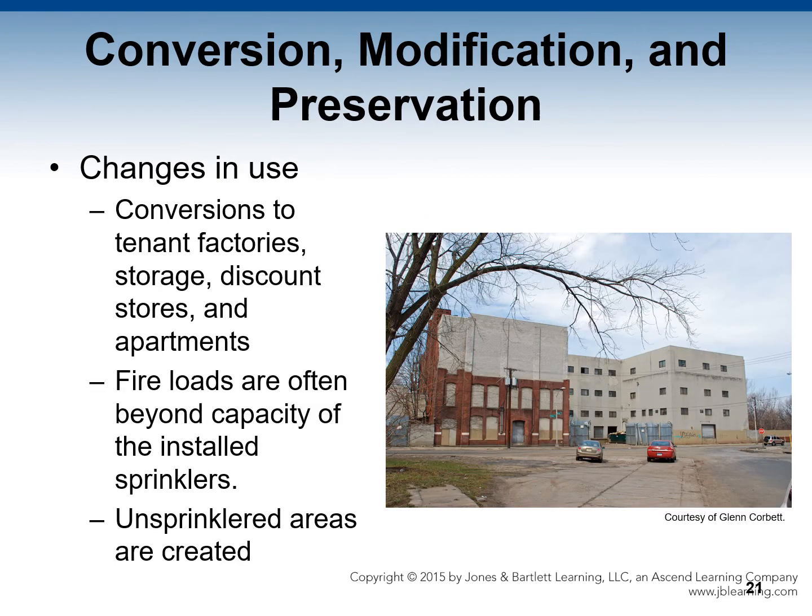And then changes in use. Conversions to tenant factories, school storage, discount stores, and apartments mean that there have been many internal changes. Fire loads are often beyond the capacity of any installed sprinklers, and unsprinklered areas are invariably created when buildings are subdivided for new use.